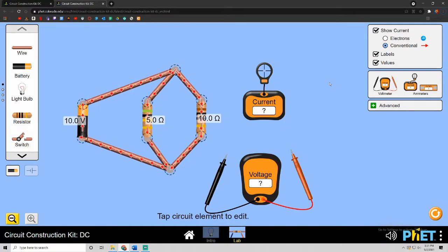we will see how the current is affected by this. Since the voltage drop across each branch is still 10 volts, we can use Ohm's law to still find the current. That being, we use the voltage dropped across, which would be 10 volts, and then the resistance of each branch. So for the 5 ohm case, we'd expect 2 amps of current, and for the 10 ohm case, we'd only expect 1. We can check this using an ammeter. We see 1 amp goes through the 10 ohm resistor and 2 amps goes through the 5 ohm. These then combine for 3 amps going through the entire circuit.